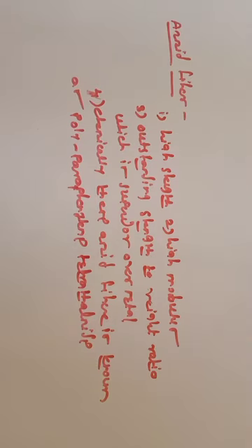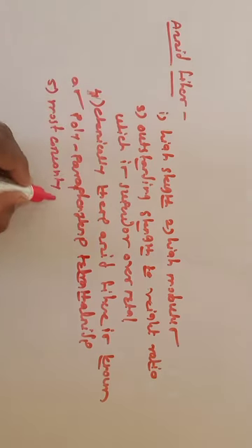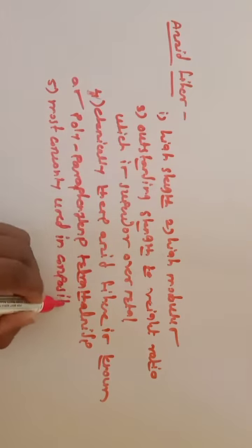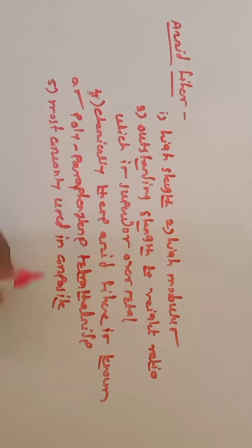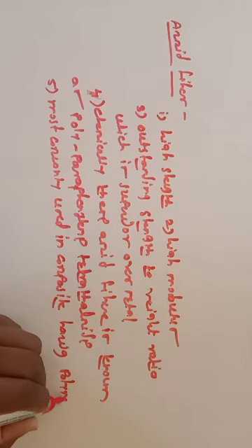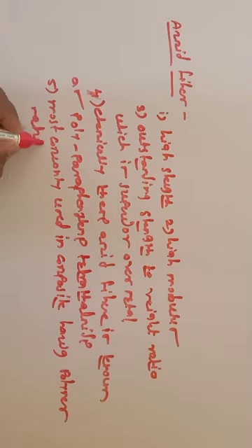These aramid fibers are most commonly used in composites having a polymer matrix. So they are most commonly used in composite materials made up of a polymer matrix, with the polymer material as your matrix and this aramid fiber as your reinforcement, such as epoxy and polyesters.